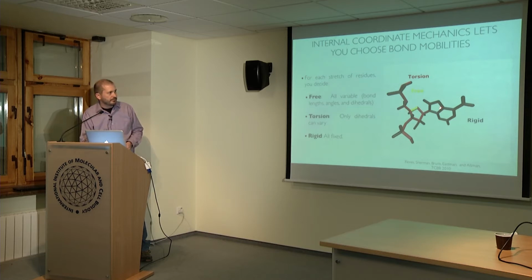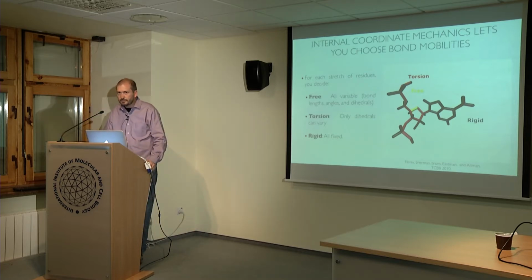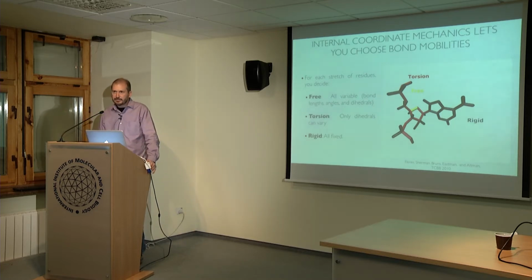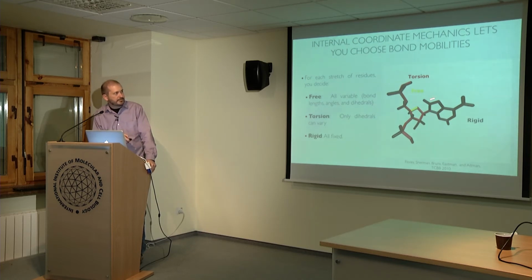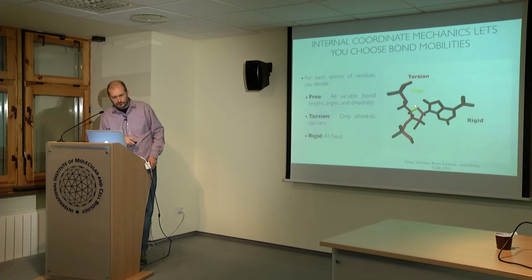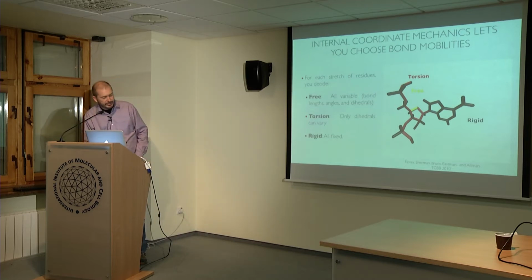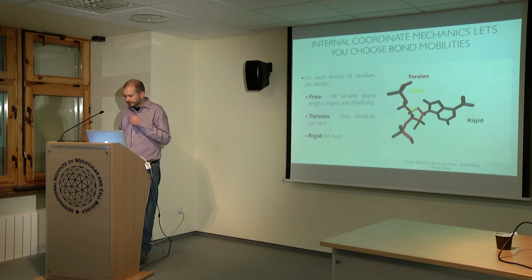You can also have this so-called rigid mobilizer, which has no degrees of freedom. So two atoms that are connected by this mobilizer are one body. And I don't mean that they're effectively one body, I mean that they are one body. This entire base is composed entirely of rigid mobilizers, therefore it has exactly one degree of freedom, and so it costs as much to simulate as a single atom would. Lastly, there are free bonds which can change their bond length, angle, and dihedral.